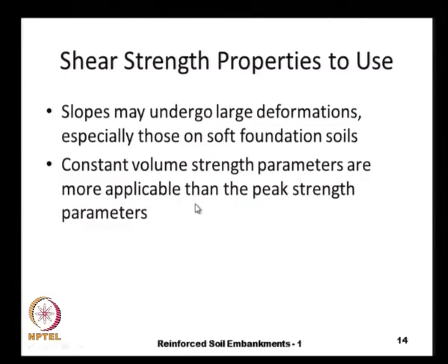These happen at very large deformations, and for the embankments or the slopes that are built on very strong soils, we can use the peak friction angle or the peak shear strength parameters.